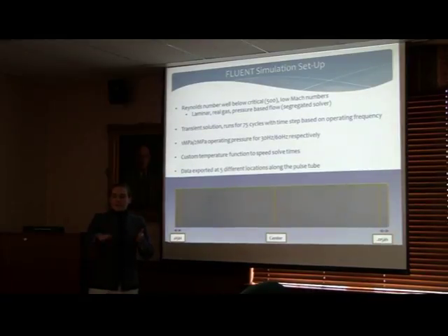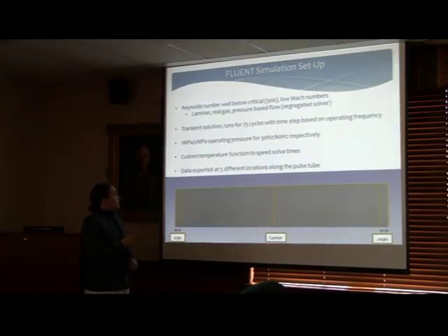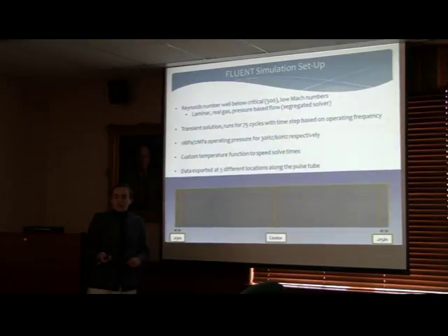So it solves that 400, and that's just one cycle. So we solved it 400 time steps, 75 times. That's why you end up with 10,000 computational hours. We also modeled at 2 different operating pressures, and this is just based on the relationship between your pressure amplitude and mean pressure. That's where the pressure ratio comes in. And 30 and 60 hertz for the 4 to 20 and 30 to 80 cases.